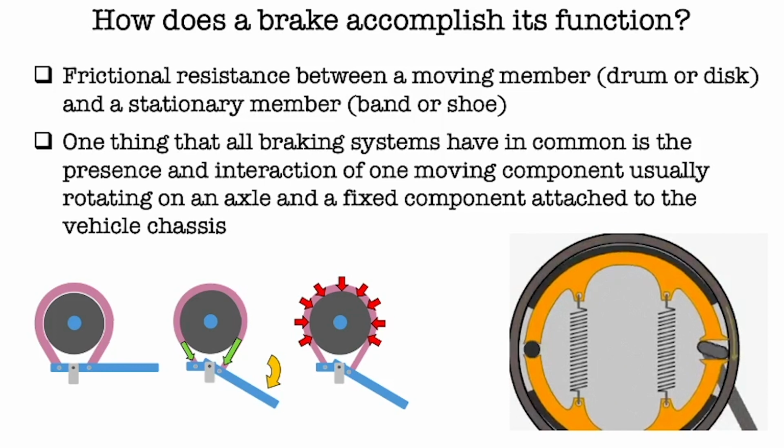As you can see in the left figure here, this is an example of a differential band brake. The band is originally disengaged while the drum rotates. Then, after applying the actuating force to the lever, the band will contact the rotating drum and push the drum to slow down or stop. Same as the right figure, this is an example of an internal long shoe drum brake. After depressing the lever, the shoe will push the drum to stop it from rotating.